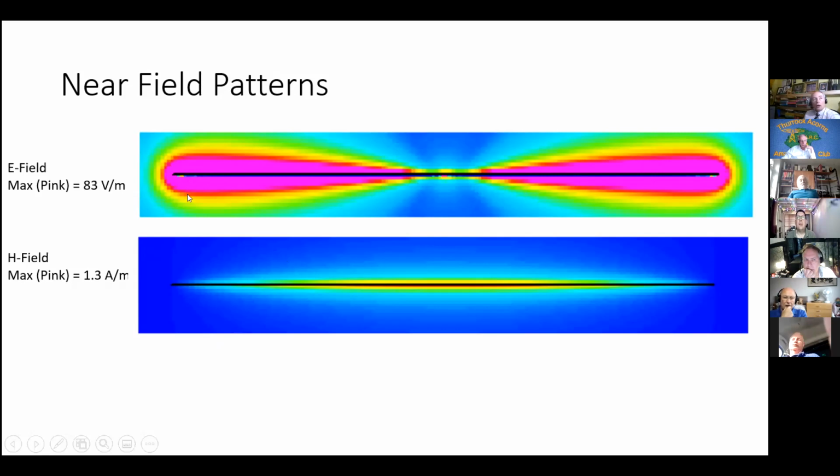And what you will see is that if that's 8 meters from here to here, 4 meters from there to there, the ends for a 100-watt station, if you like, the safety distance is about 1.5 meters. The pink contour is maximum field effectively, and I set that to 83 volts per meter, which is what you need for the ICNIRP 6-minute power.